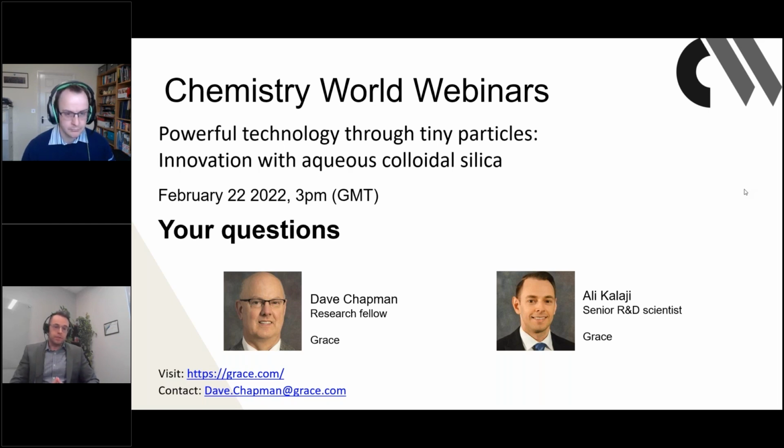Another important consideration for particle size is whether you're looking for monomodal particles or polymodal. With polymodal, you have multiple different particle sizes in the same colloidal silica, and you can imagine the small particles filling in the gaps between the large particles. So that would be something to consider if you're trying to make a very dense film of silica.